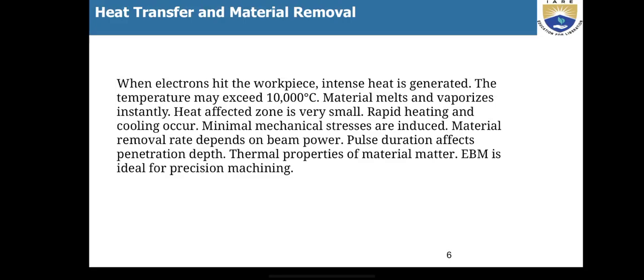Heat affected zone is very small. Rapid heating and cooling occur. Minimal mechanical stresses are induced. Material removal rate depends on beam power, pulse duration, and penetration depth. Thermal properties of the material matter. EBM is ideal for precision machining.